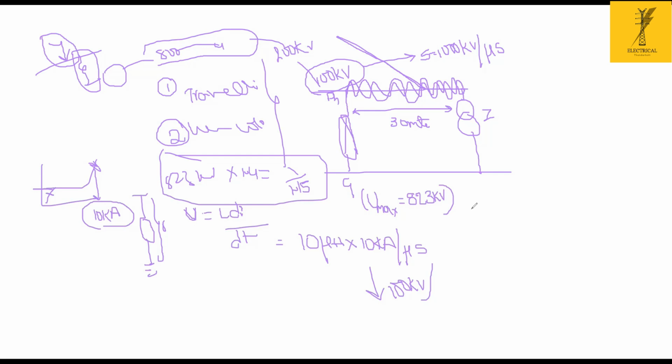In a simple way, when you are choosing the lightning arrestor, always two conditions are to be checked. One is the distance between the arrestor and the device to be protected. The other is the overvoltage stresses in the system. These two we generally get from the insulation coordination study.